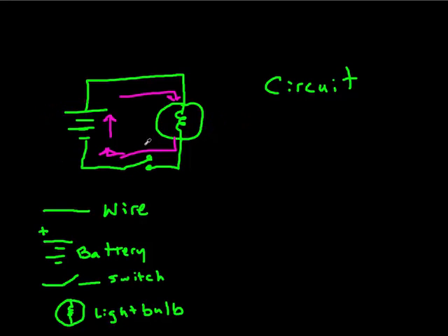It's a pretty simple concept, but what it's really saying is the conservation of energy law, and that is that there cannot be any more energy consumed in a circuit than what is provided into the circuit. And likewise, the energy provided into a circuit has to be consumed by the circuit. It's pretty simple here because you've got one load device, but in a little bit we'll have more than one load device, and you'll start to understand how that voltage gets divided up across those devices. So that's what KVL is all about.